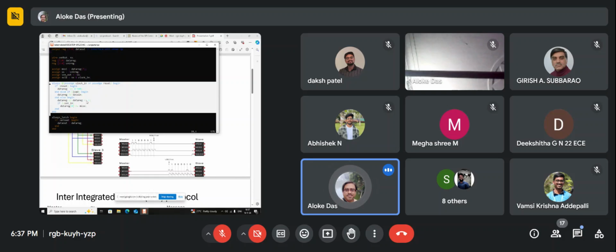And this operator, double less than, means each clock signal it gets one left shift. When you give left shift, data comes out from the MSB side of the register. If you want the data to come out from the LSB side of the register, then you have to give right shift. So adjust those things carefully, then you will get this working. Again, this is a recommendation and guidance, but you are free to do it in any way possible.